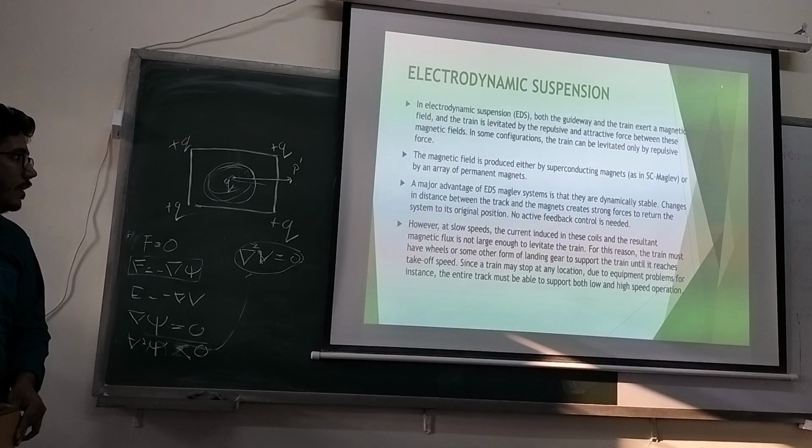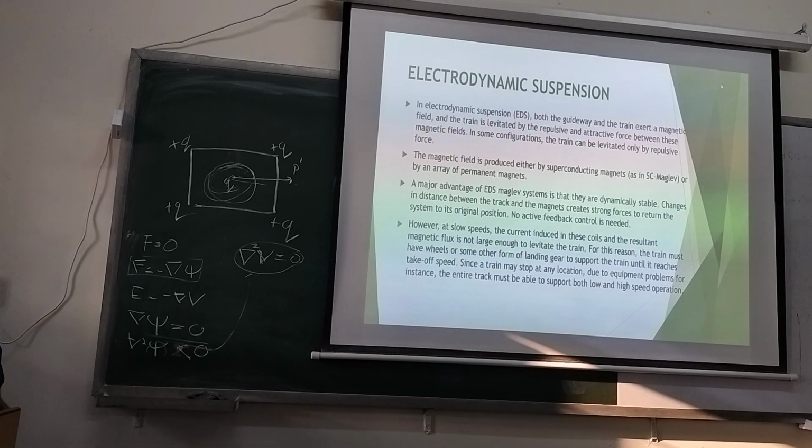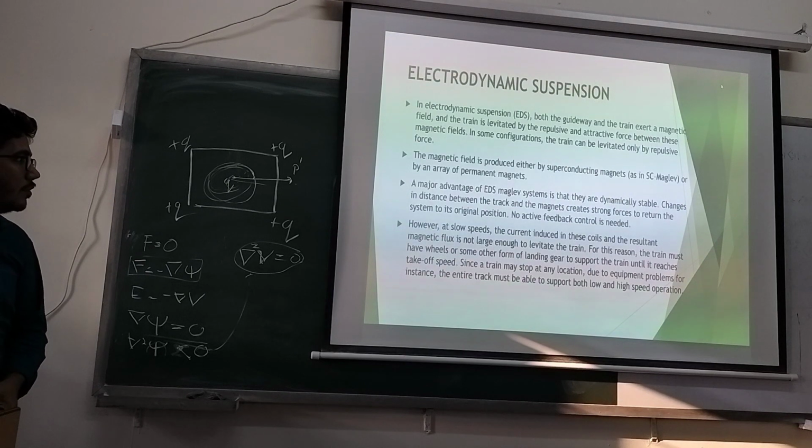The advantage of the EDS magnet system is that it is dynamically stable. Changes in distance between the track and the magnets create strong forces to return the system to its original position. No active feedback control is needed.